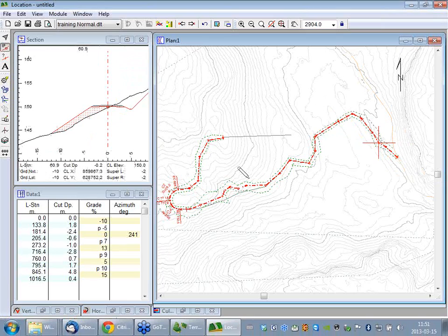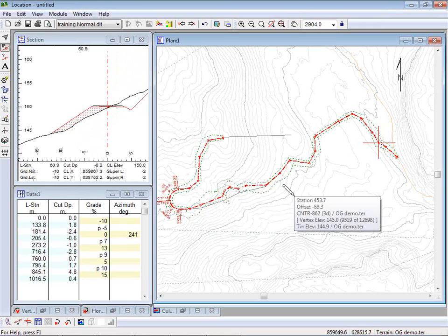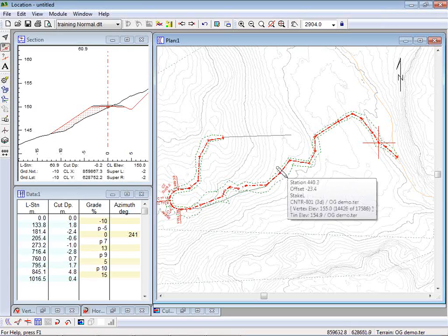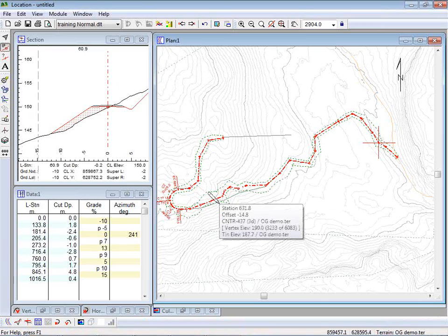Or this material that's sitting at 50% side hill is actually unstable, and we can't even do a full bench cut to cross it. It's going to be a problem. That's the kind of information you're going to get on the ground. But the Lidar gives you everything else. Now, I pretty much used up my time. I was going to show you a quick introduction to our optimizer software.